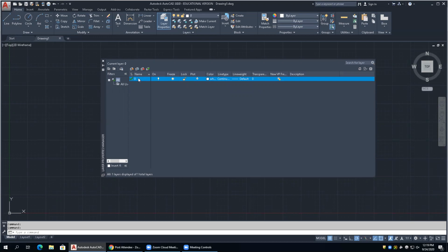Okay. I used to do it when I first started AutoCAD. I just called them layer 1, 2, 3, 4, 5. Two weeks later, I'd come back to that drawing and, well, what the heck's on layer 2? I don't know. So I'd have to figure it out. Okay. The name can be up to 256 characters. It can be alphanumeric, space, underscore, $, hyphen, but you can't use a slash or a backslash because those are switch characters in Windows. Okay, so it won't let you do that.